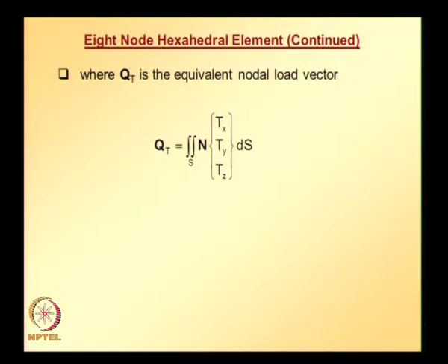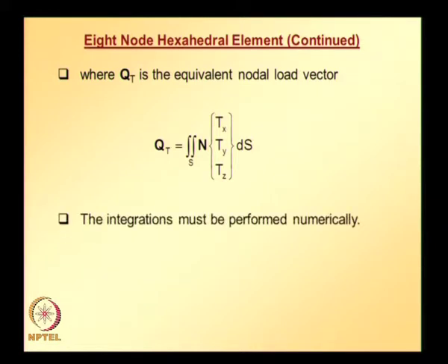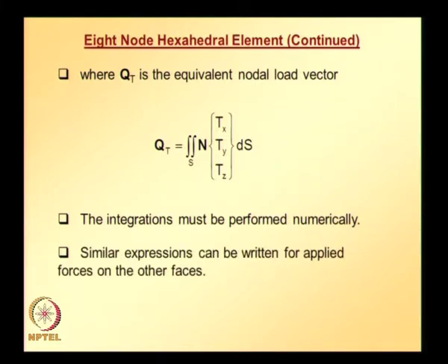And this is going to be a surface integral for the 8 node hexahedral element. So, the integrations can be performed numerically, similar to what we already looked at in the earlier classes for evaluating integrals in 2 dimensions, and similar kinds of expressions can be written for other kinds of applied forces, body forces and other forces.